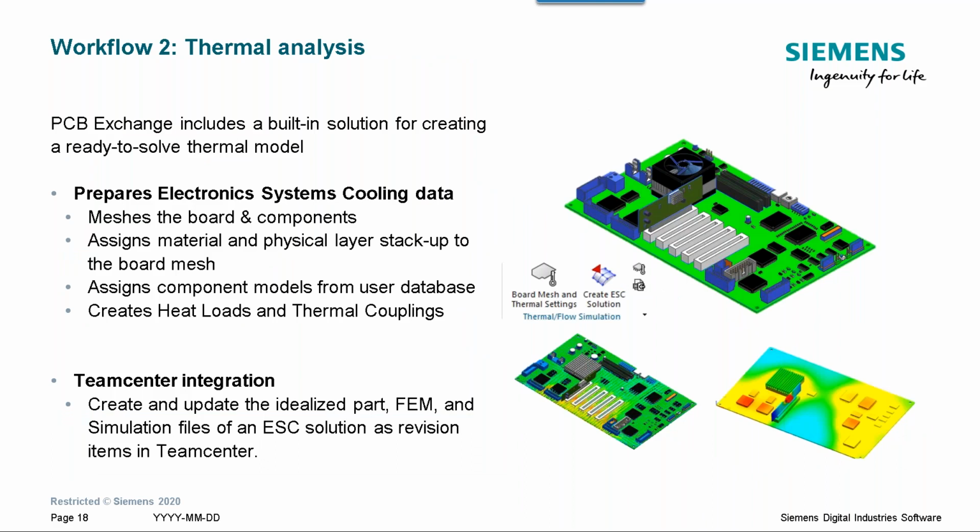So as I mentioned, once we import this data from ECAD, NX or Simcenter 3D understands the full data model of the PCB design. And basically, we leverage this to streamline the creation of the thermal model. So what we do from PCB exchange is to create a ready-to-solve thermal model.